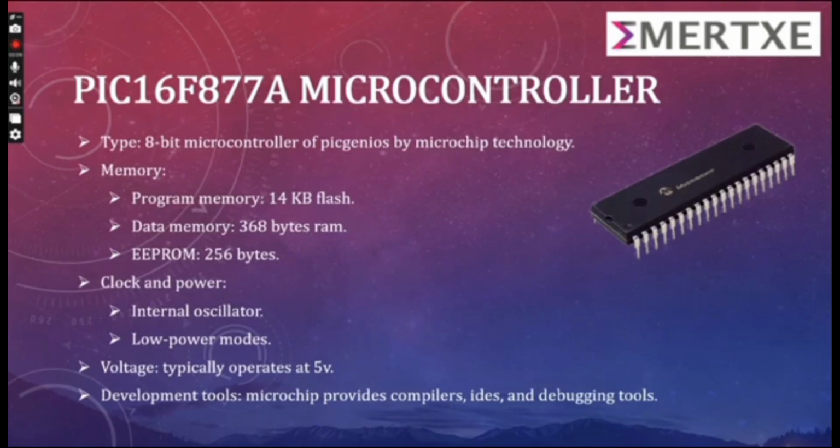This is the microcontroller that we used during our project. It is the PIC16F877A microcontroller, an 8-bit microcontroller of the PIC family by Microchip Technology. The memory involved is program memory, which is 14 KB flash, data memory, which is 368 bytes RAM, and EEPROM, that is electronically erasable ROM, which is 256 bytes.